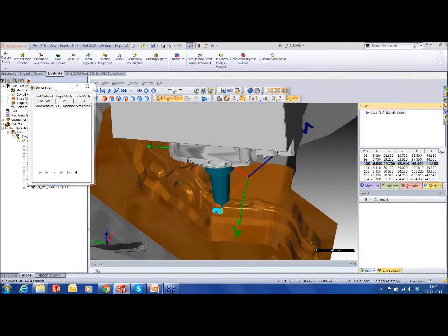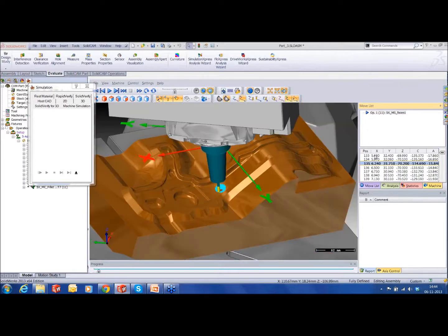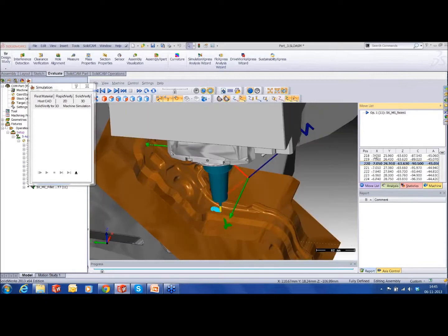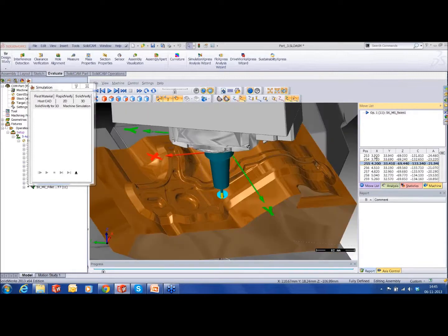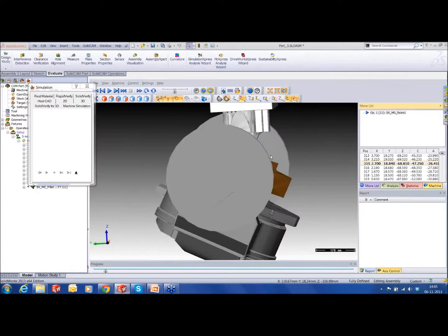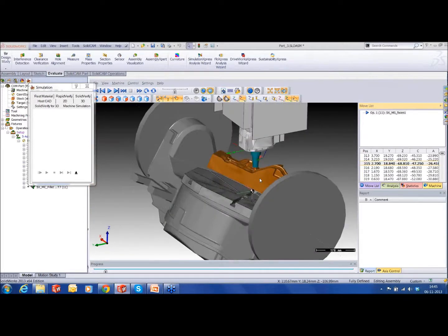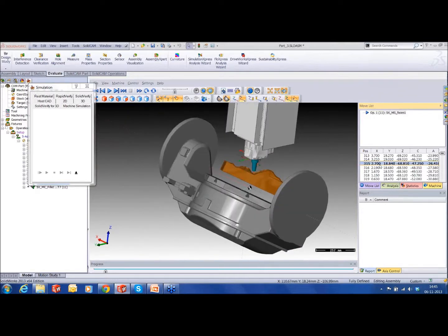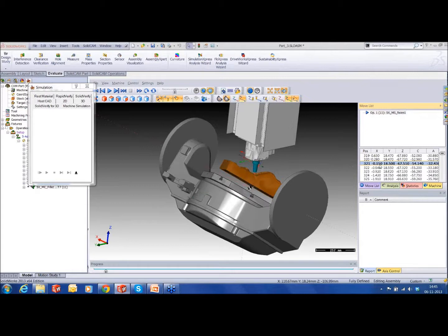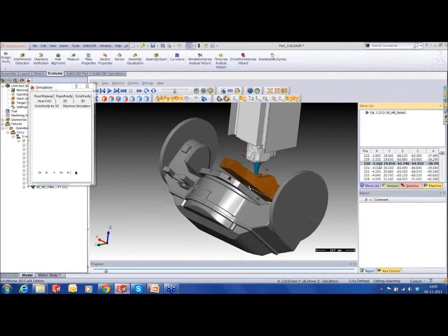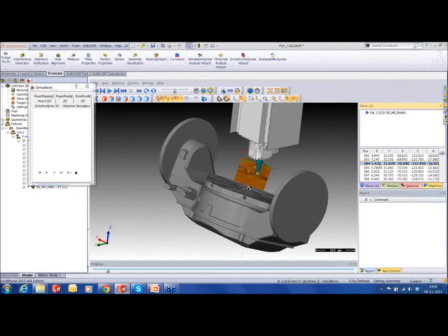You can see how nicely and easily the cutting happens. Remember that we are using a very short tool out here, just 20 millimeters out. We can even cut that because we don't see any kind of gouges happening. If you're looking at this part from a bit further away, you can see that there is absolutely no gouges happening, and it's doing it in a very fluidic motion.